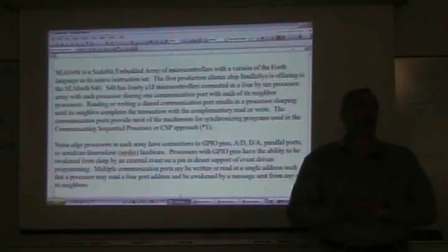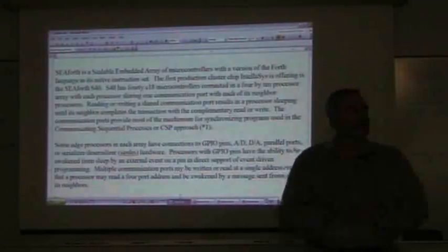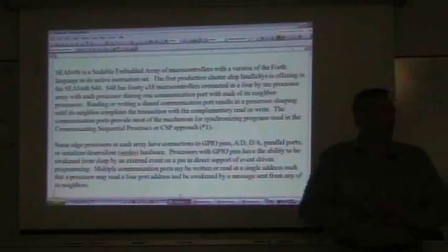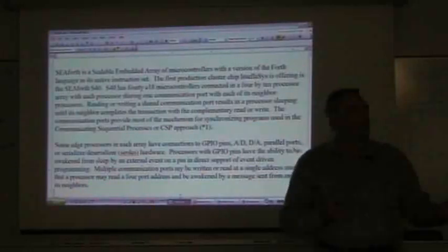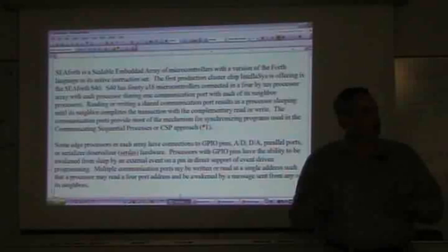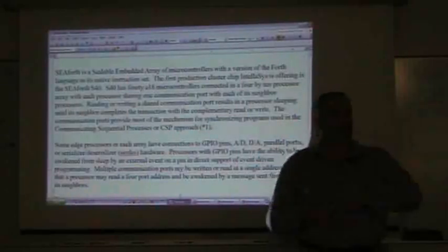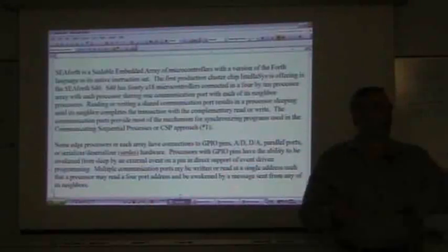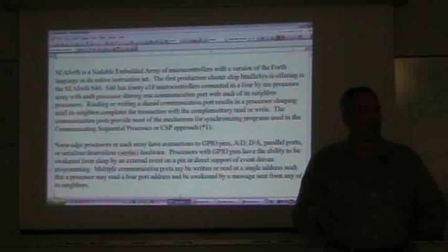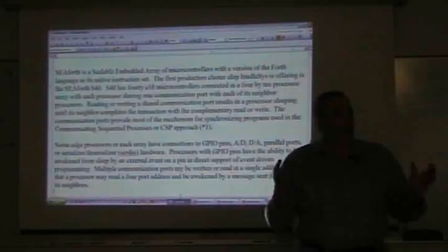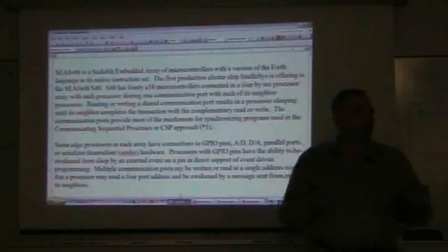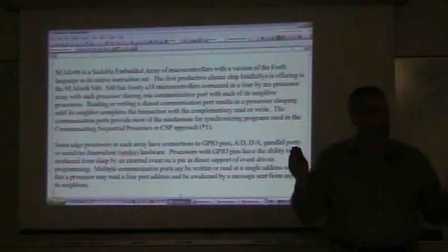Our design has a hardware implementation of Forth. What you used to think of as much of Forth is gone. It's moved into the hardware. We don't have to implement dupe as a string of opcodes, and we don't have to implement drop and over and all of these things that you have to implement in a virtual machine in a normal Forth system. Those are our opcodes.